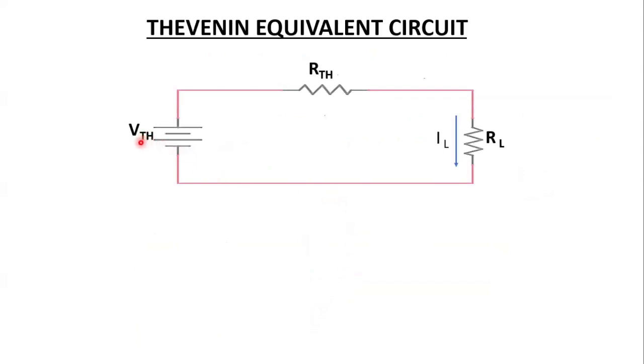We have a new value of the voltage, which we call the VTH, and another internal resistance of the source voltage, which is the RTH now. And then we connect back the RL, since the unknown is the current in the resistor RL. In this case, when the value of the RL is changed, it's not difficult to find another value of the IL.